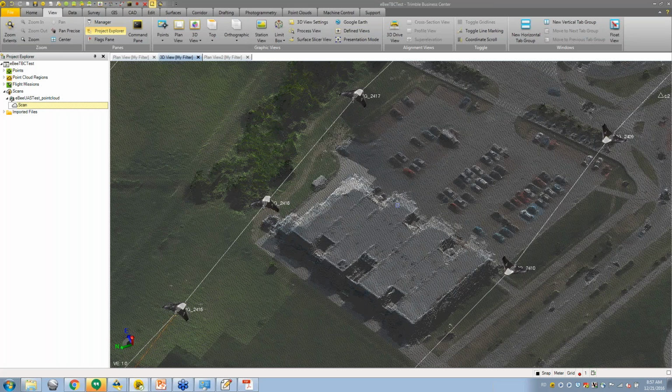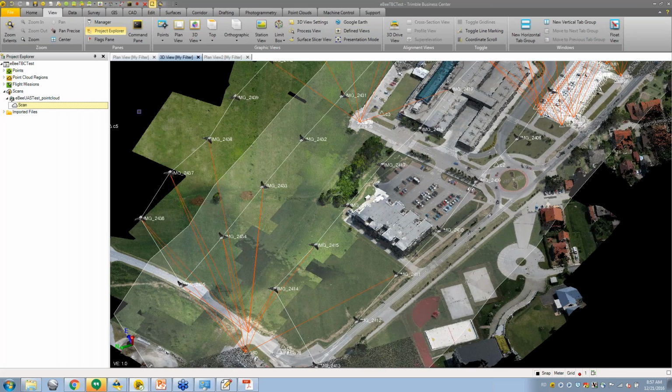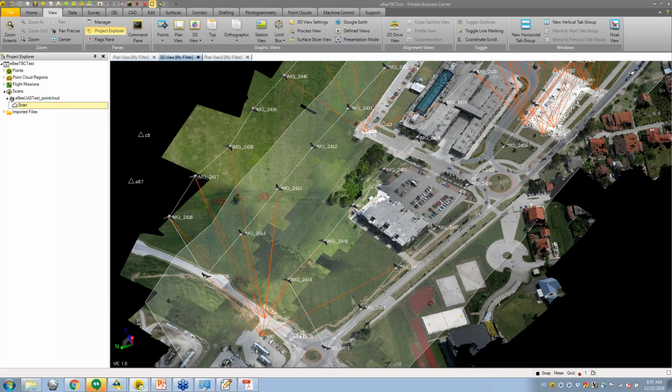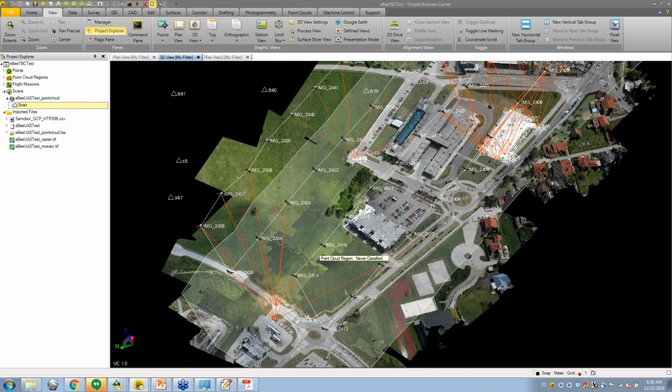After the import, you can view and pull these into any other TBC workflows you would like to do. You, of course, would want to go through the next steps of editing your point clouds before you send them back to TBC. As you can see, it's pretty easy, and with that straightforward workflow, you can get done. Especially your first project will take some time, at least getting the parameters set correctly and calibrating correctly, but after you have that step done and you become a little more familiar with editing within UASMaster, you can get a project done very quickly. You can process very quickly in UASMaster.